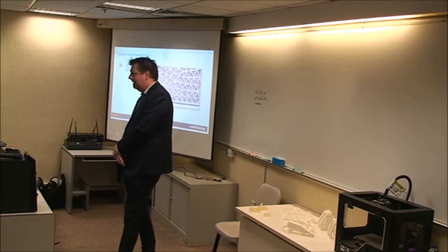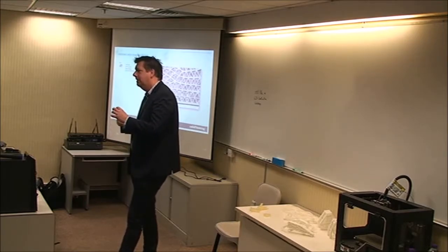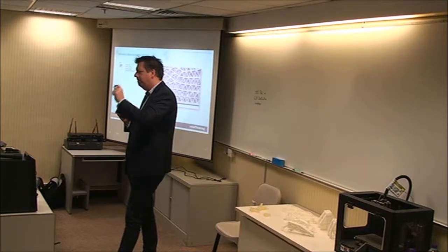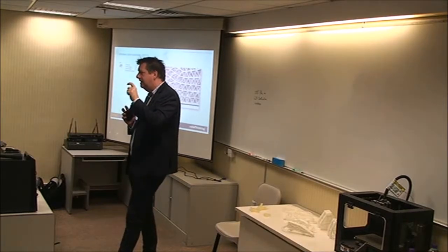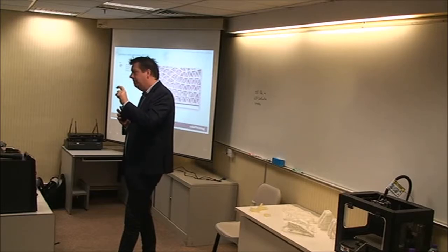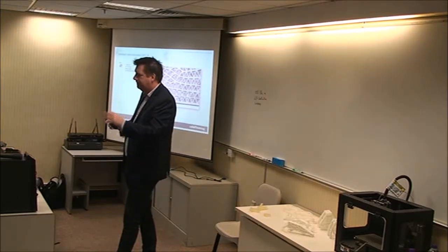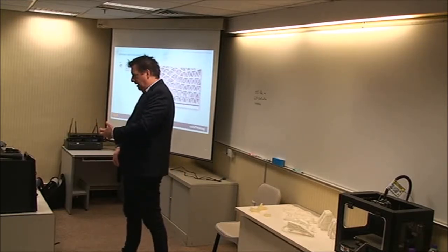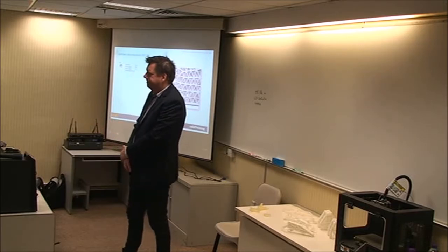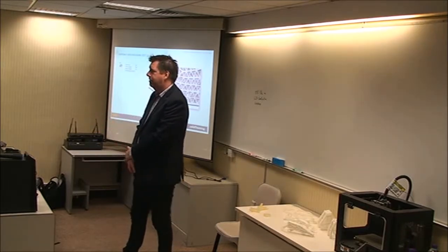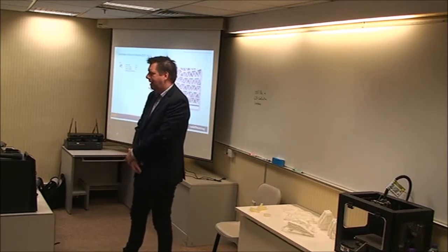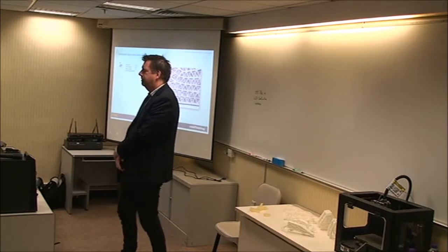So you can see there the beams are tapered. So our process with the lattice structures is to build a mesh and then optimize the radius or diameter at each end of the beam. So you get these tapered beams all through the structure, which gives some really, really nice looking results. So other people do lattice like mapping your lattice onto your parts for 3D printing, but that really is just map conformal, like a consistent lattice onto your part. We actually optimize it for structural performance.